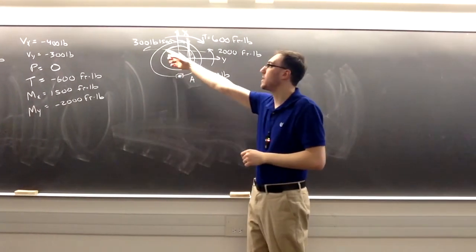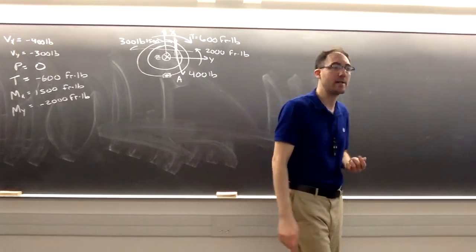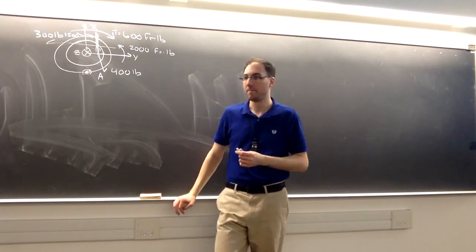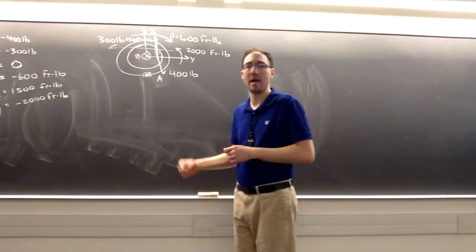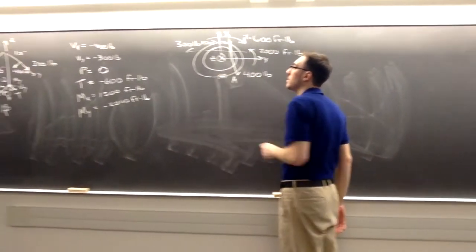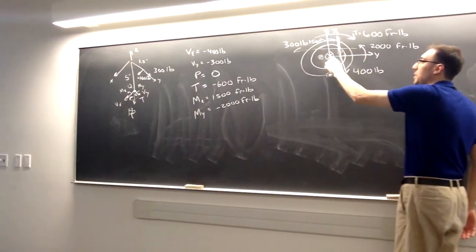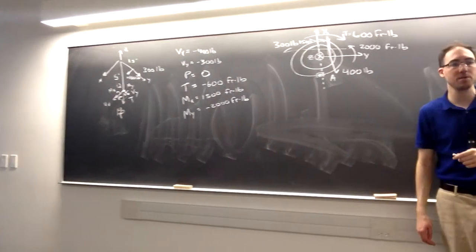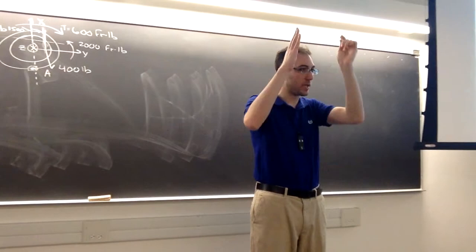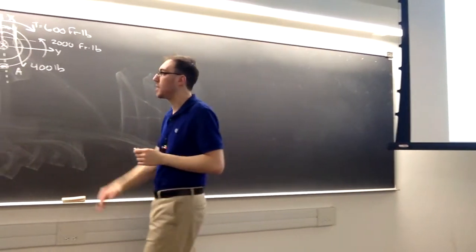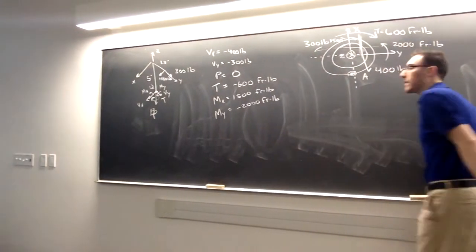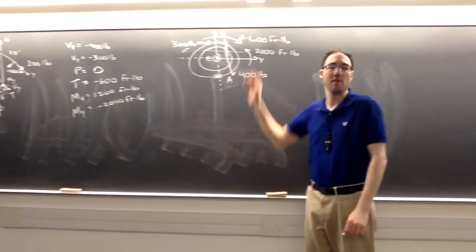However, from the viewpoint of the 300-pound load, where is A located with respect to the 300-pound load? Right, it's perpendicular, and it's along what axis specifically? Which is also, right. So with respect to that 300-pound shear force, A is along that neutral axis. So we now have to think not only along the vertical, but along the horizontal. We have two neutral axes to worry about because we can have loading along now two directions.